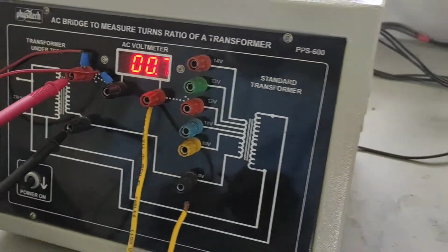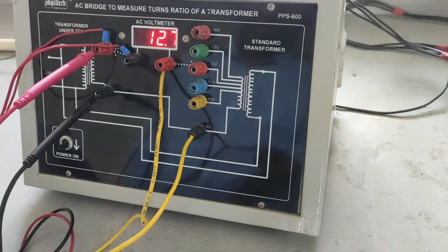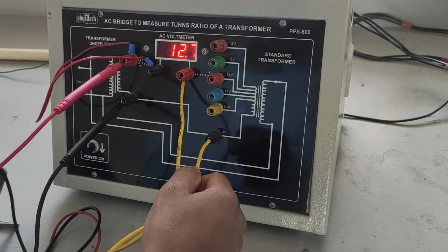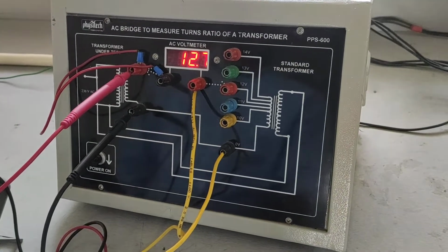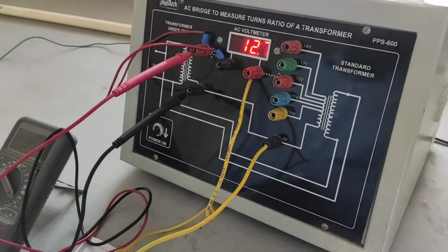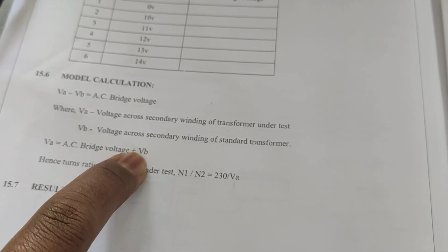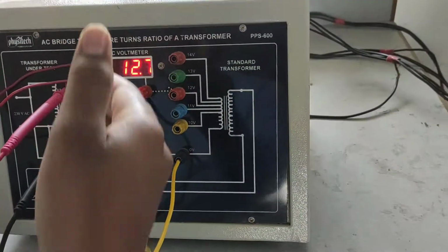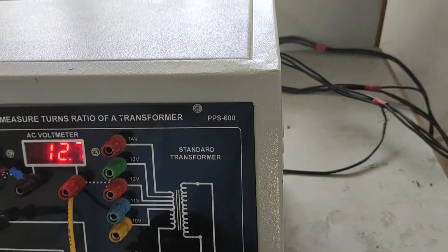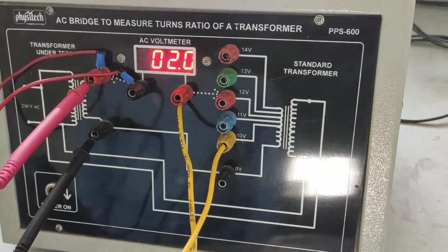When you check the voltage at the 0 volts position, that means we are taking a complete winding of this transformer. In that case these two are internally connected, so it is 12 volts and 12 volts, and you have taken only the 0 tapping. 0 tapping means we are not going to consider the winding of the standard transformer. That's why this voltage is 0. So if you see the formula, AC bridge voltage is equal to VA minus VB. This VB voltage is anyway 0. So the VA voltage is whatever the voltage appearing across the transformer, that is 12.63, nearly 12.7, that we are getting here. Now by changing this terminal, instead of 0 volts, if I connect it to 10 volts, 12 minus 10, we will get the difference as 2.